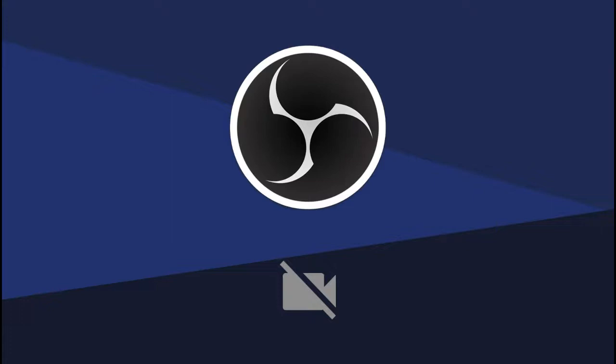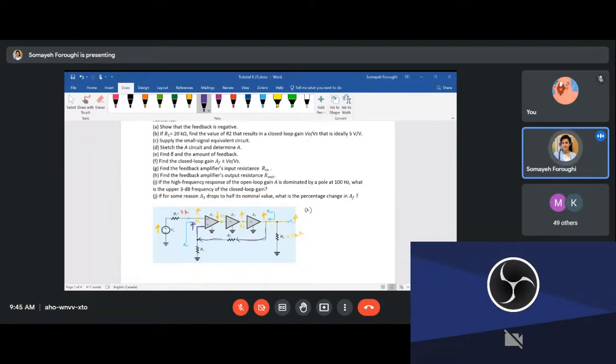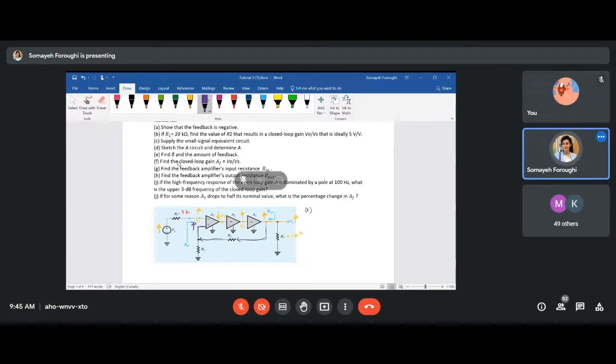This terminal voltage is also increasing. I'm going to write it down, don't worry. And now, as you see, we have increased voltage on both terminals of the first amplifier. It means the difference between, let me name this one V4, the difference between V1 and V4 is either kept constant or it's decreasing. And that shows that we're working on a negative feedback amplifier.